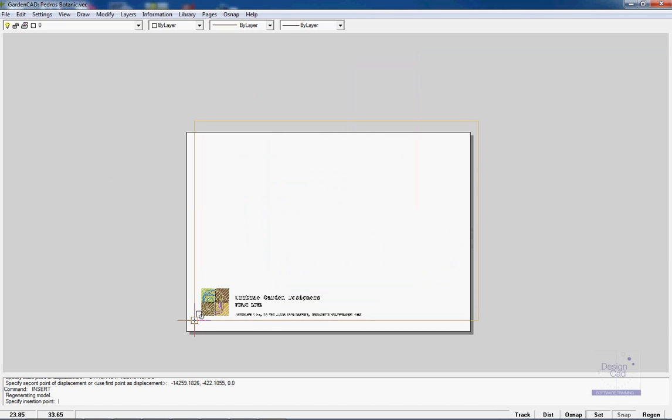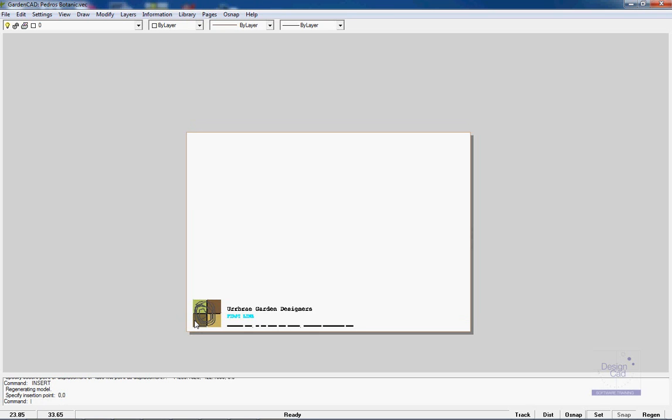And you can see it nearly fits the A1 sheet, which I've set up previously as a page. So let's put it in at coordinate 0, 0, and in goes the block. I'll deal in a moment with attributes, but what we want to do is to put our side and section view of the tank and the seats on this sheet at a defined scale.